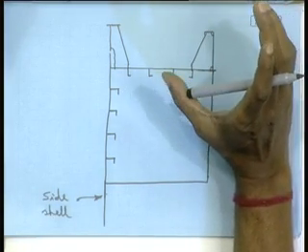It is good in case of structures which are subjected to longitudinal bending, and when a structure is subjected to longitudinal bending, in the event of compression it suffers buckling. So, what is important is buckling strength, right. So, now if longitudinal framing system is adopted, then it will give you a better buckling strength. A better buckling strength means your critical buckling stress will be higher. So, due to longitudinal bending it will not buckle, right, that is what is important.